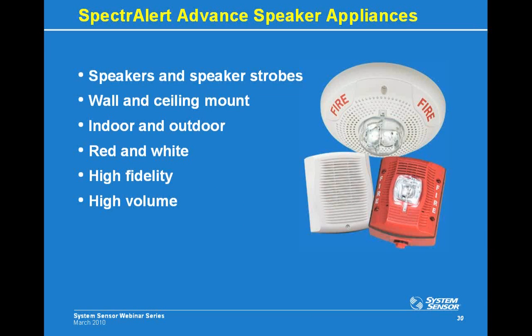Now that we are coming to a close to this webinar, I would like to briefly mention some of the System Sensor products that round out our speaker offering. We offer speakers and speaker strobes that are available in wall and ceiling versions for both indoor and outdoor applications, and are available in both red and white. We also offer two different versions of our speakers as well. Our standard speakers are what we call our high fidelity speakers, and these will aid in intelligibility. And then we also offer what we call our high volume speakers, which will provide approximately an additional 3 dB output at each tap setting.